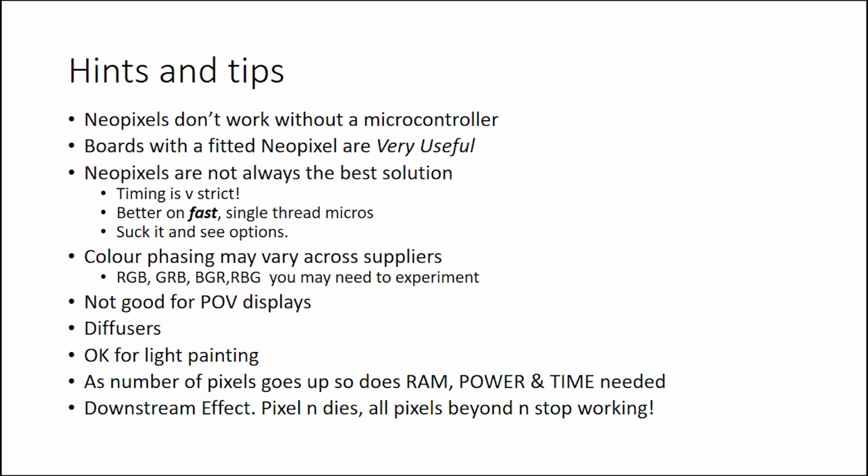Couple of hints and tips. This is the boring part of this, but we're very nearly finished, so please hang with me. You need a microcontroller. You can't just buy NeoPixels and put electricity in them and expect to see light. Doesn't work. Boards fitted with a NeoPixel: that little RP2040 has got a NeoPixel on the back. The cheap yellow display, the CYD boards.